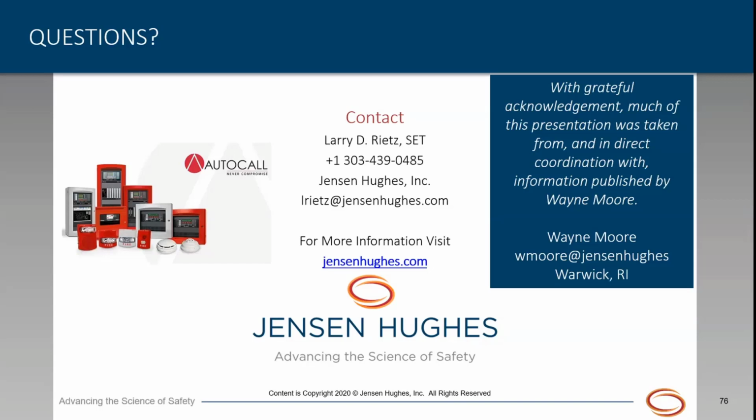Okay. Do you want me to read the second one again, Larry? I do. Okay. Can CI cable be landed on a panel while maintaining the CI listing if it is not in a 2-hour rated room? Technically, no. If it's not in a rated room, and it should be, the control equipment should be, then technically just connecting CI cable to that control panel would not meet the intent of the UL listing.